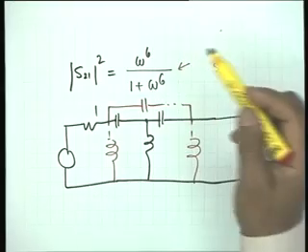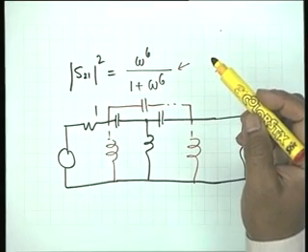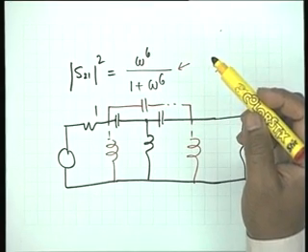Let me ask you a trivial question now. Sir, can we assure that there would be only 3 elements? Oh yes, that we can be sure because there are only 3 poles. Because the order of the function here is 6, it is a magnitude squared. So the magnitude would be of the order 3 and therefore the function would be of the order 3. Now a trivial question. Could we have, instead of omega to the 6, could we have omega to the 3 here? No. Why not?